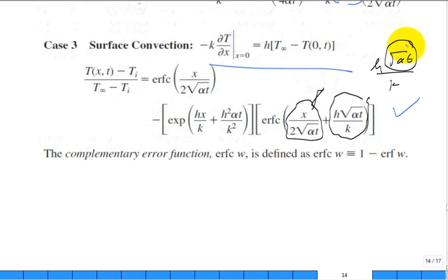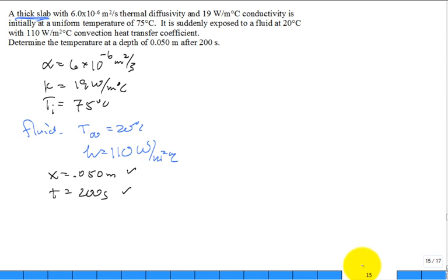That looks like a Biot number. All right. But you have to compute these, then use the complementary error function and exponential, etc. And you can then go ahead and make a calculation. The eta for this problem comes in at 0.722. The h square root of alpha t divided by k comes in at 0.20.